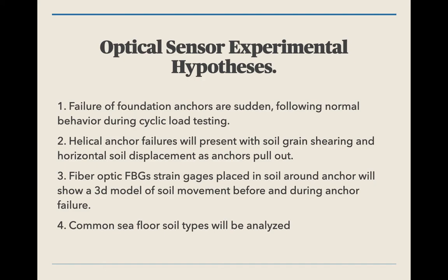So I have, in my traditional scientific way, come up with some hypotheses. The first of which is that the failure of foundation anchors is sudden, following normal behavior during cyclic load testing. The second is that the helical anchor failures will present with some kind of disturbance in the soil, proceeding very soon before the anchors pull out.